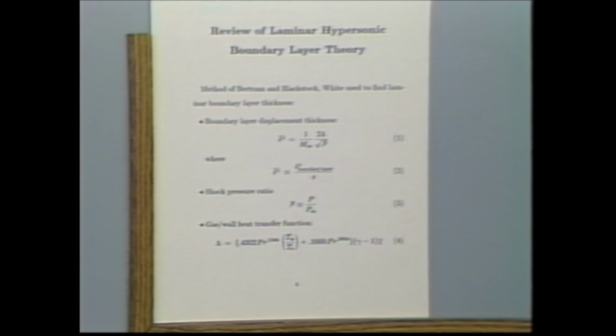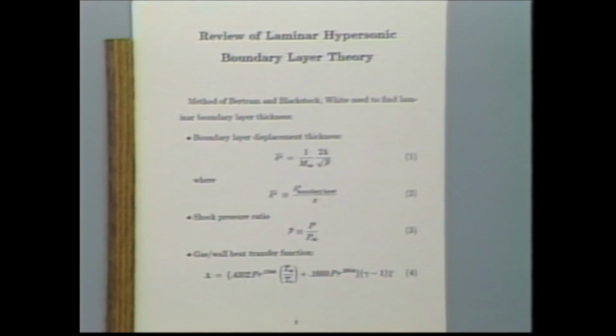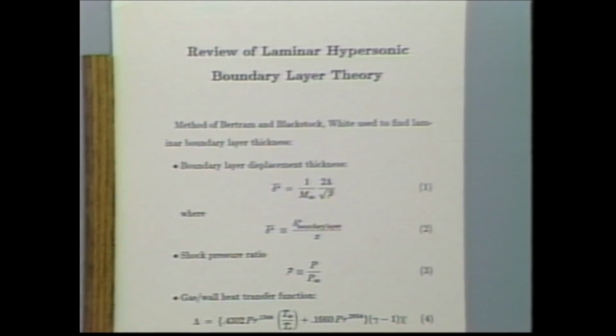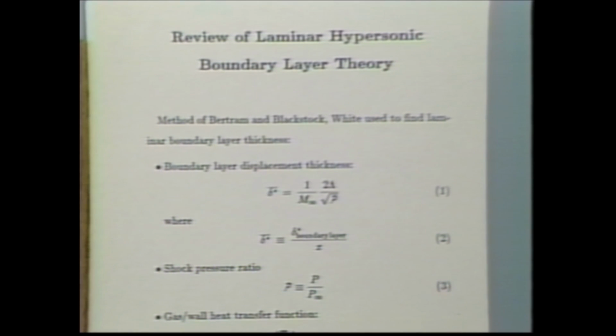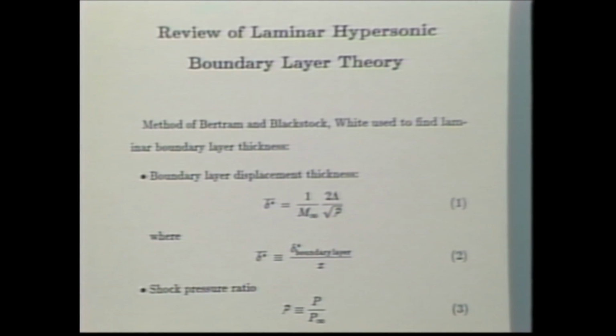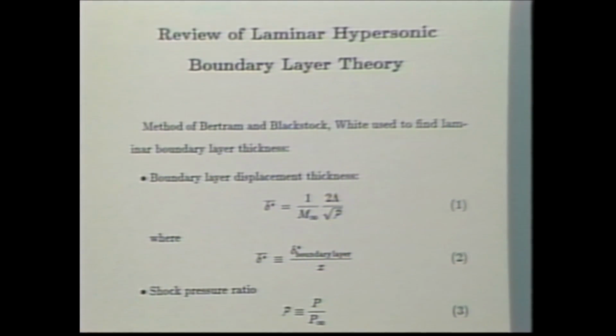Yesterday you had a fairly extensive discussion of hypersonic viscous flows, and I want to touch on some of the key points that will be necessary for today's talk. As those of you who are familiar with the boundary layer concept know, there are a variety of parameters that we use to characterize a boundary layer. We characterize a boundary layer based on its frictional effects and its heat transfer effects, and also the way it interacts with the free stream flow, or the inviscid flow sitting above it. And in order to evaluate that, the most convenient parameter is the boundary layer displacement thickness.